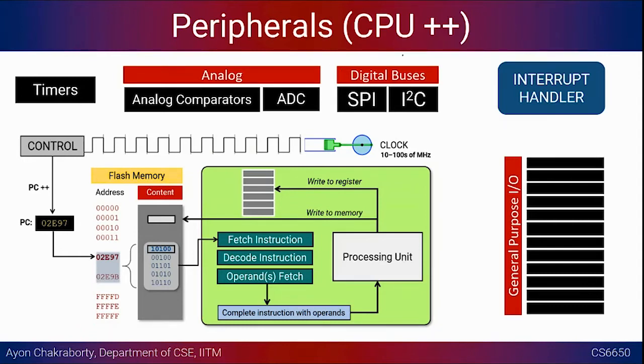However, there are other sensors which are just going to give you digital data. Instead of giving you analog data, they will convert it into a digitized form and send the data out to be consumed by the microcontroller. However, you need to have certain rules for negotiating how to fetch the data. The sensor will not understand any arbitrary way to get the data. So there are certain ways you have to interface them, and I'm going to teach you two specific interfacing techniques that hardware also exists in these microcontrollers.